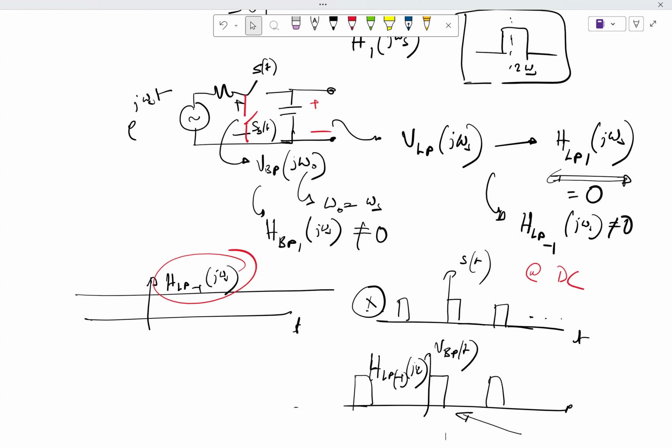This is not a universal truth. Another key point to take away is that across the capacitor, approximately only the zeroth harmonic exists, and everything else is zero. It almost behaves like a low pass filter with the RC time constant of RC.